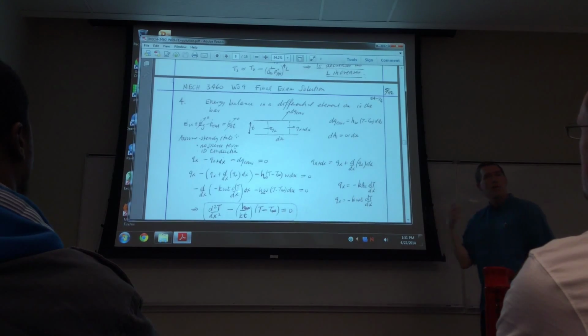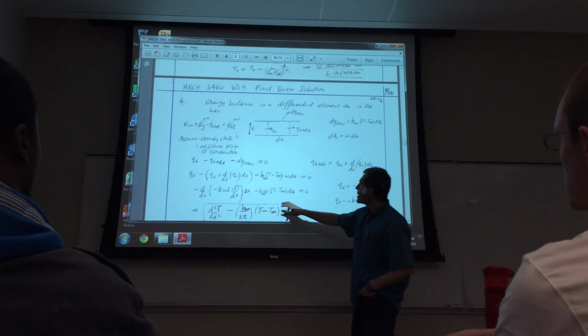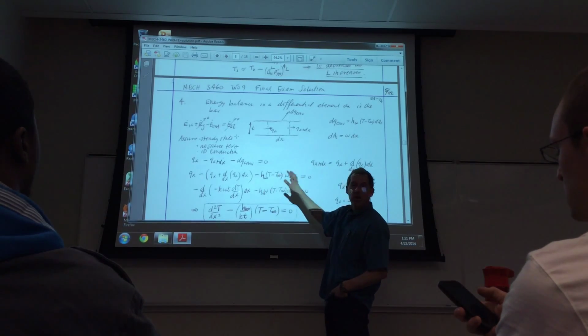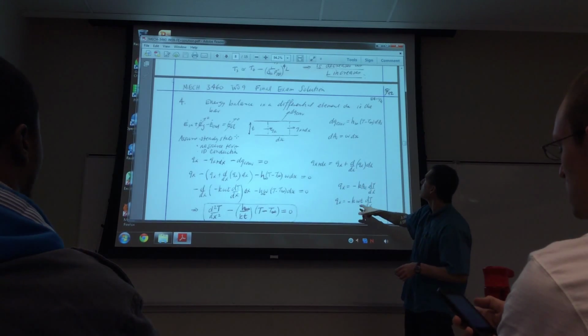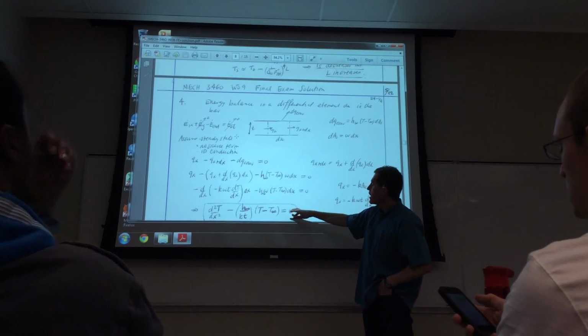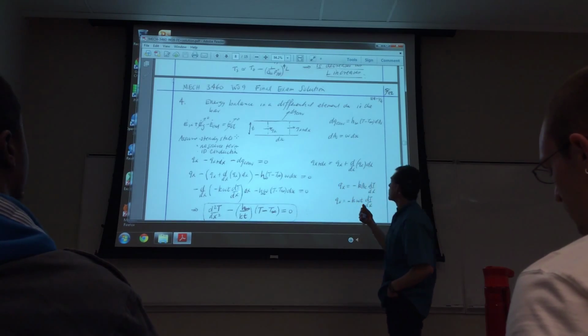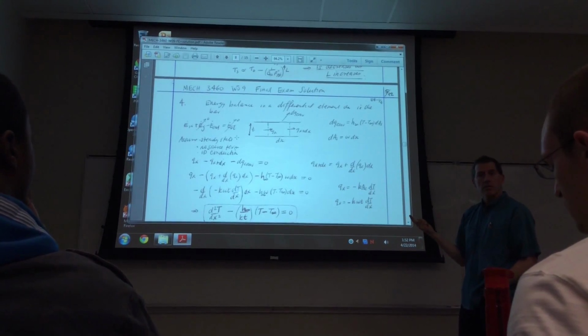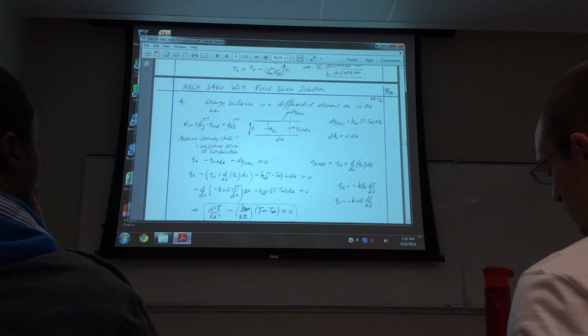Okay, now, I had a few people ask me about this in the last week of classes. I know another way to do this is just to leave the perimeter in there. Go to your standard fin derivation. Another way of doing this is to take the standard fin derivation and put in W as the perimeter and WT as the cross-sectional area, and then just use that as your fin equation. Did I put that as the alternative here? I think you had an alternative solution at the bottom of it.